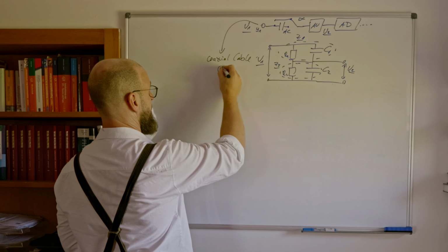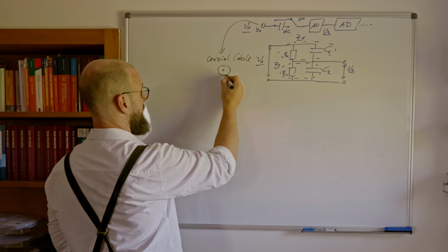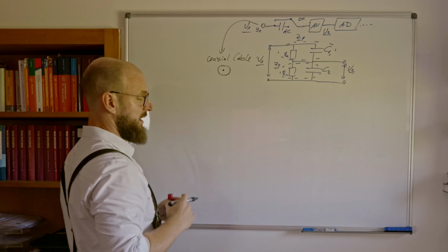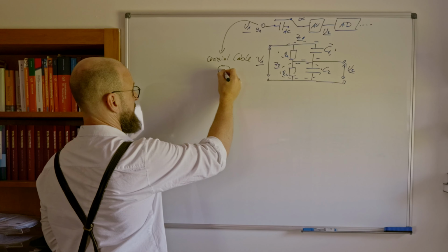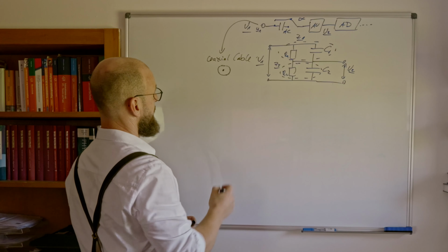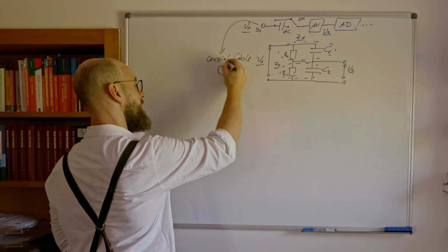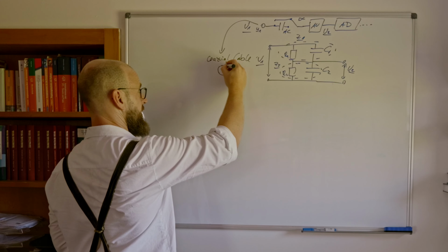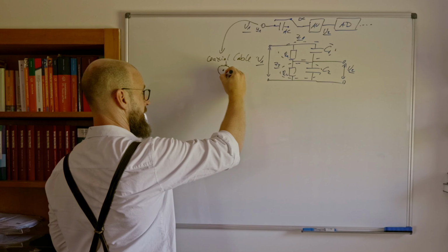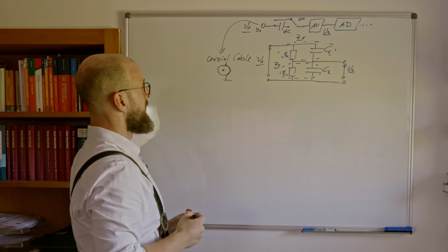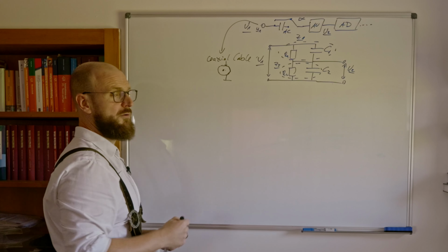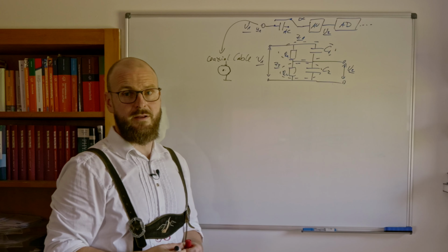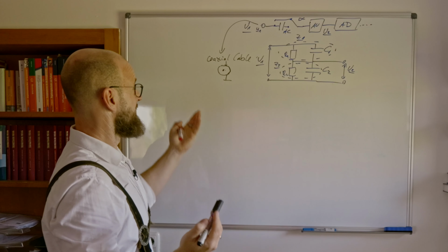It's nothing more than the ground at the outside, building something like a cage around the measuring line, which is not the ground, which is in the center. And that gets you to the fact that any signal coming along here will be directly fed into the ground and will not disturb your signal in the middle of the wire, in the center of your wire.